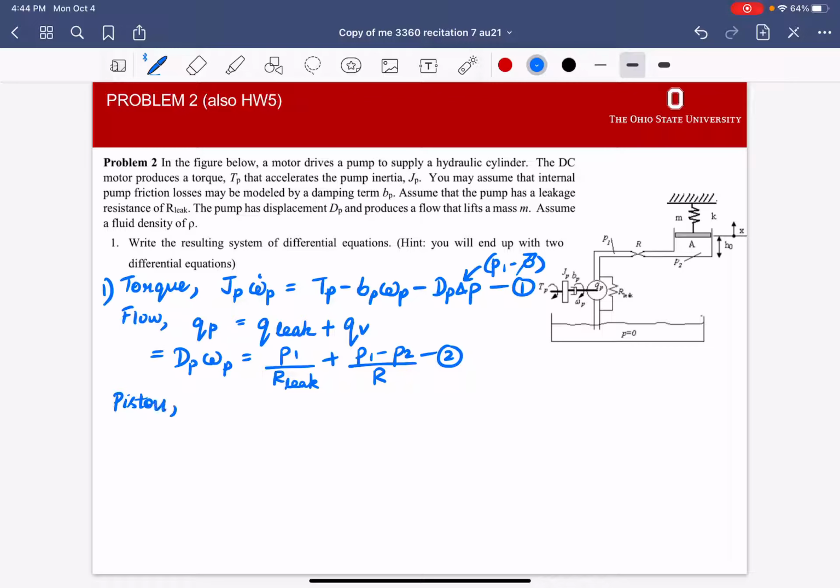All right. So finally we have the equation for our piston. Now we are looking at this object over here. There will be some hydrostatic force, which you're learning about in ME 3503. So there's some force coming in from the fluid below, hitting the piston head, and then there will be some force coming in from the spring from the top, and that would be equal to the mass times acceleration of this piston head.